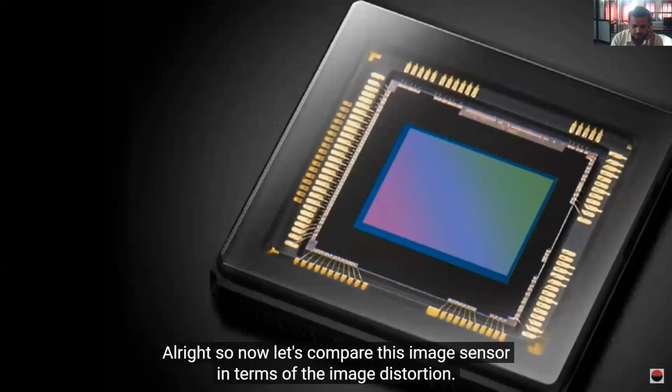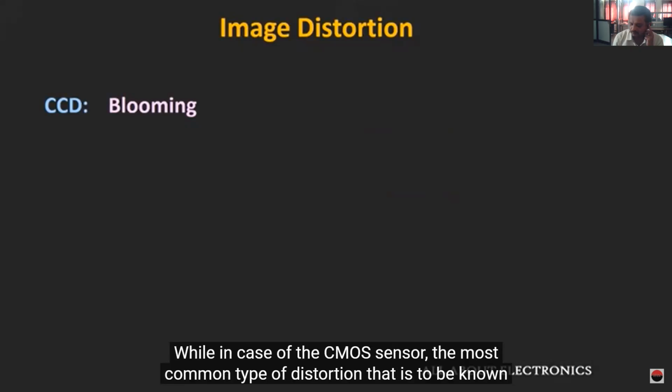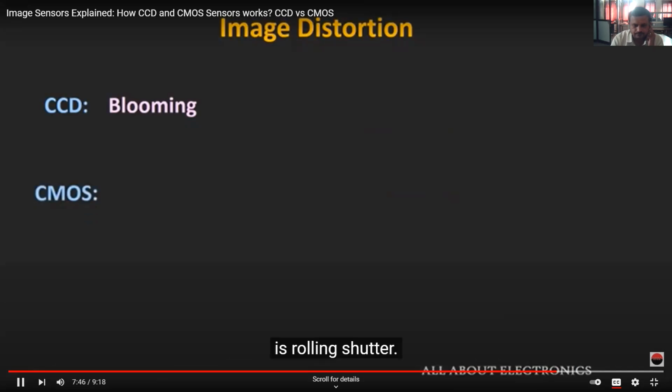All right, so now let us compare these image sensors in terms of image distortion. In case of the CCD sensor, when you expose the sensor for a longer time, you will see an effect known as blooming. Nowadays, by using anti-blooming techniques, we can reduce this blooming. While in case of the CMOS sensor, the most common type of distortion to be known is the rolling shutter.